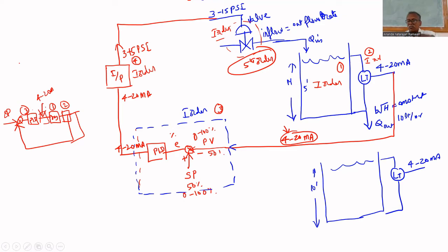That's why oscillation comes. Suddenly if anything happens, you cannot take a decision. With oscillation, we are very close to the J omega axis. That's why oscillation comes into the picture. So here, this is minimum fifth order. That's why you cannot increase the gain of this PID controller beyond a certain value. So we have to fix the value, so that one reason is the system must be stable.